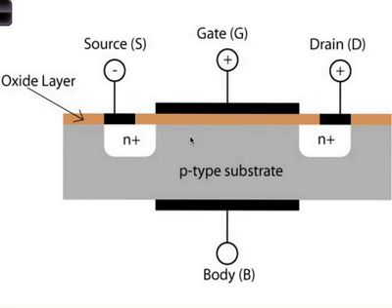You have a P-type substrate. You have an N+ region on this side, so you have a drain, N+ to P. This PN junction is typically reverse biased, as is this PN junction in normal operation. Okay? So what happens is that when you apply a positive voltage to the gate, you push the holes away and you attract electrons to the small region near the interface, and you create an electron channel.